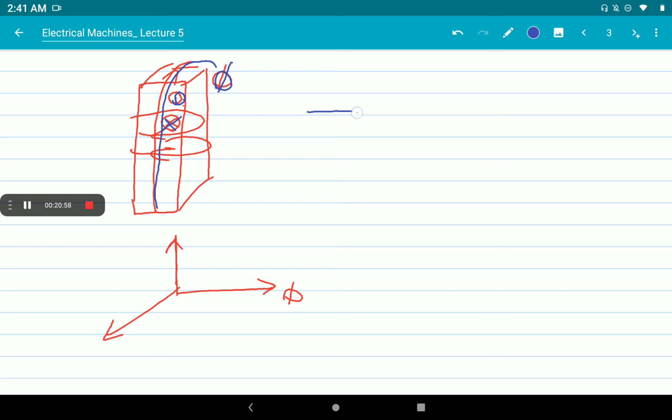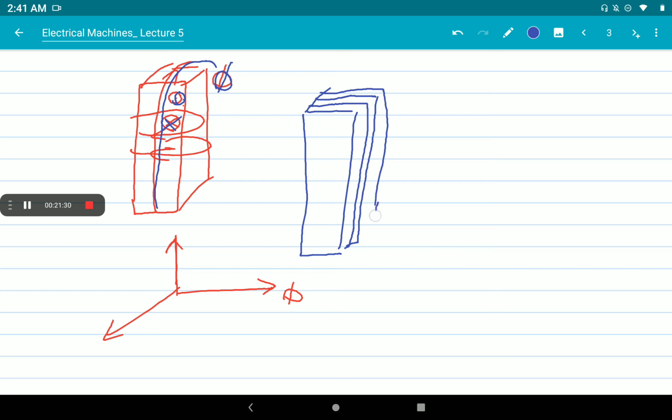Just consider when we take a magnetic sheet of metal, then again another sheet of metal is stuck on that first metal sheet, and we are placing a varnish or paper, an insulating material, in between that. And again we are taking another metal sheet and sticking it on that, and similarly we are placing more and more sheets and making the same thickness of core.